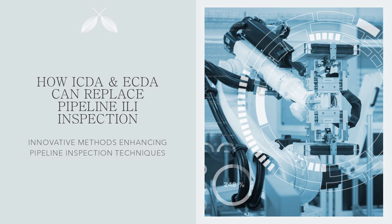Welcome everyone. Today, we're going to explore how Internal Corrosion Direct Assessment or ICDA, and External Corrosion Direct Assessment or ECDA, can serve as practical alternatives to traditional inline inspection, commonly known as ILI. These methods are recognized by NACE standards SP0208 and SP0507 and are increasingly accepted by regulators. Our goal is to understand why these approaches are important, how they work, and why they can be more cost-effective and flexible compared to ILI.